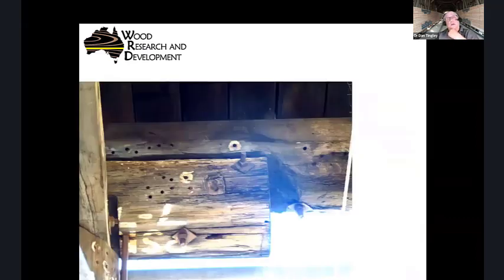Bore sounding's the old way. This is bore sounding on steroids. You just keep drilling holes in it. You know, it was good in 1900 when labor was cheap. We didn't care how many times we replaced a girder, but that doesn't work today. And where are we drilling? Where we put the verticals. And we put the vertical and it splits it. So what do we do? We put an anti-splitter bolt in, and then it splits it in four ways. And so we're drilling more holes.